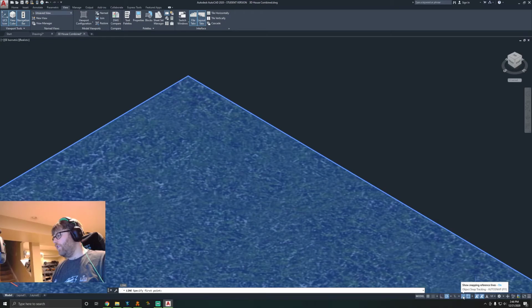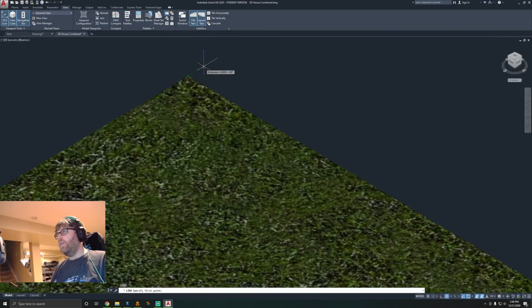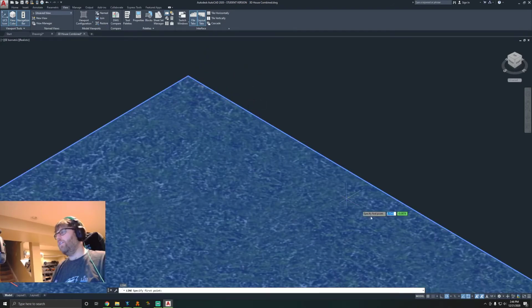And this is actually the tracking. So that's that extension line. It'll track where you're going. But this one here, the square box, you can choose what you want it to actually snap to. These are the ones that I typically have on. So if you want it to look like mine, you could have endpoint, midpoint, center, quadrant, intersection, and extension all on.